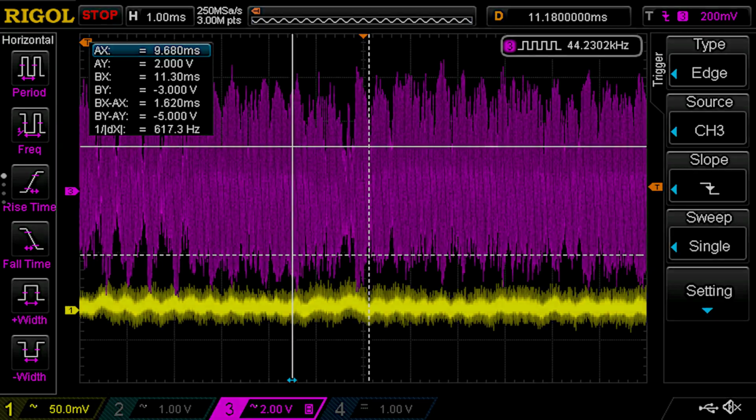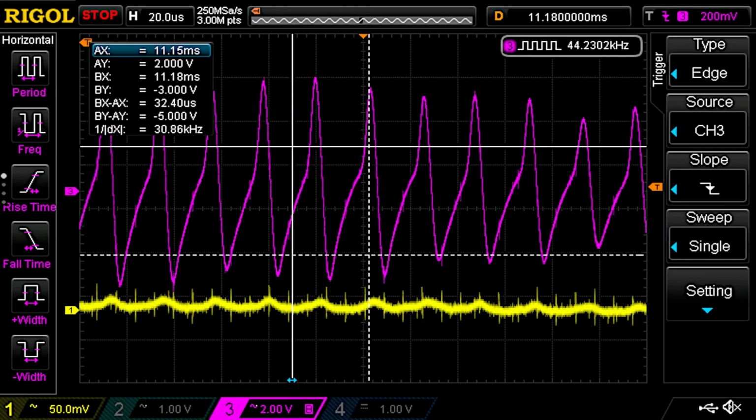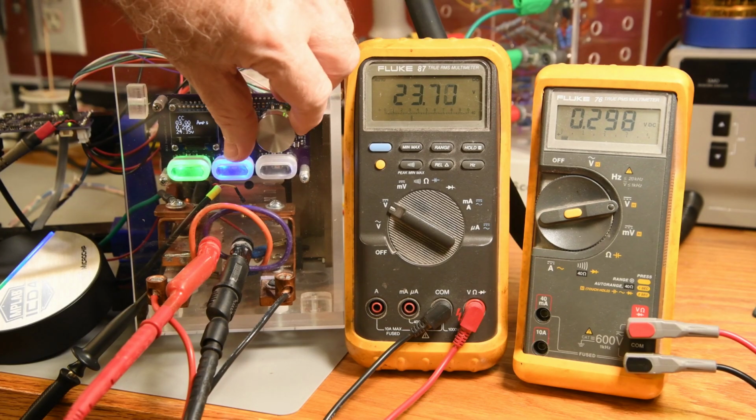That is horrible. Here, with the sweep set to 20 microseconds per division, you can see more of what is going on. I have an oscillation at around 45 kilohertz. I'm quite sure the fact that the DAC data is being updated at 45 kHz is not a coincidence. I'm just surprised considering that the circuit's gain at 45 kHz is so low. While I believe the root cause of this problem is in the MOSFET power modules, I'm hoping I can deal with it in the software, at least make it stop oscillating.